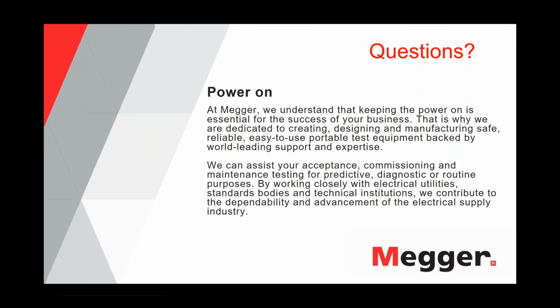So when you have a mixed cable, and let's say you would have a cable where you have 90% XLPE and 10% paper, you would measure basically the tan delta of the paper, and because it's a high value, it might mask how good or how bad the XLPE is.